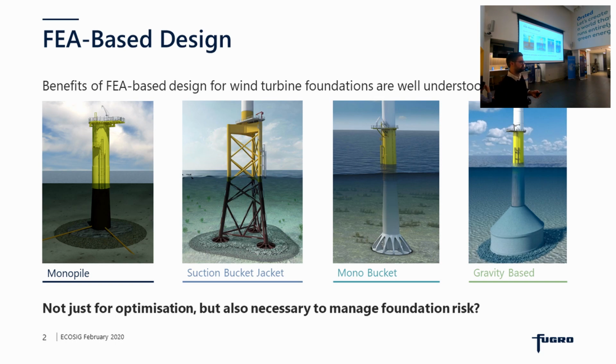So some soils may respond in a way for which current design methods provide a cautious representation, but there are also soils which respond in a way for which current design methods may provide a non-cautious representation. Perhaps that's where the focus needs to be. I think acknowledging the fact that we're looking at risk as well as reward from these analyses is particularly important.